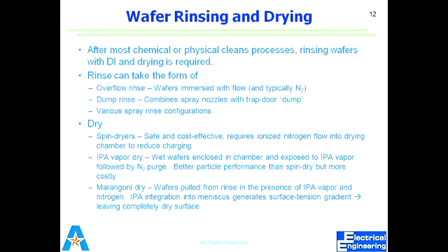In that environment, when you have the wet wafer inside IPA in vapor phase, IPA gets on the surface and water is removed. Then you take that IPA coated wafer outside. IPA is an organic solvent that is very volatile, so it evaporates very fast. So when you take out the IPA coated wafer, it evaporates very fast, and that is another way to get the wafer dry. At the same time, you blow nitrogen on the surface as well, so that you make sure there is no water residue on the surface.